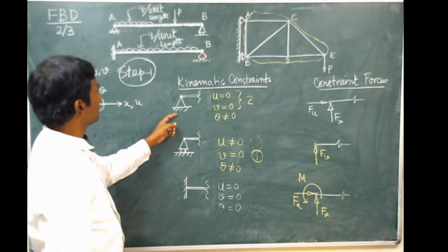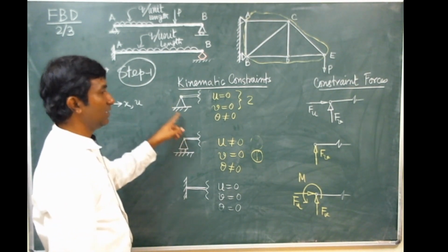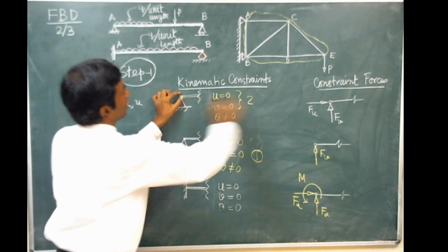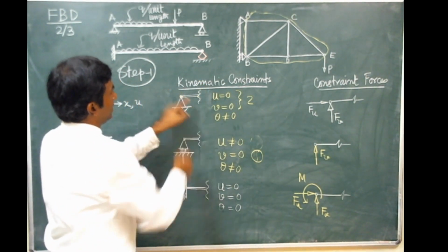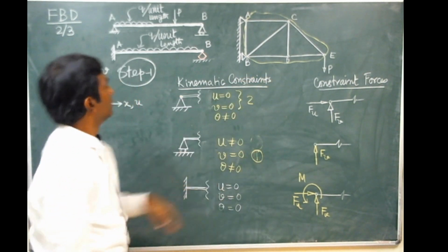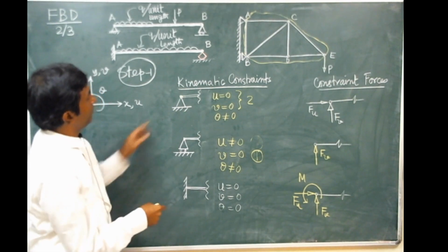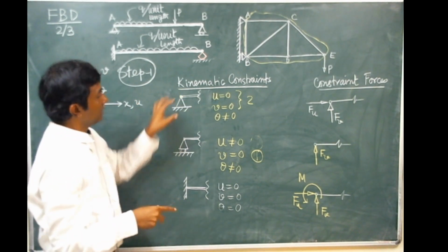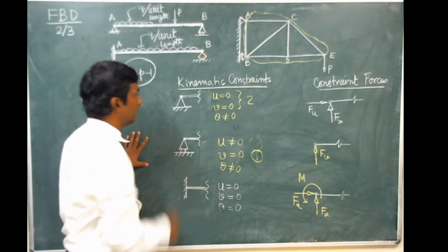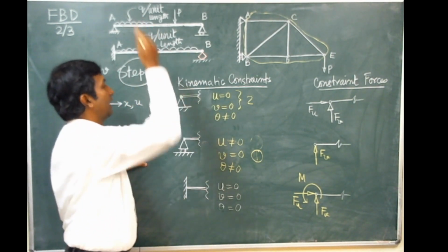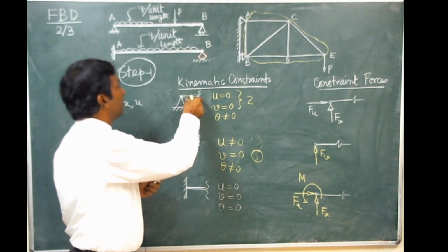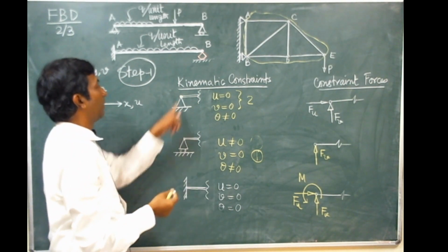You consider this case where this joint is a hinge joint. This is a member, an extended member, so we have not extended it. This is a formal representation, that means that this part is extended. So we see the meaning of that representation. This kind of representation means displacement is not allowed in the x direction, displacement is not allowed along the y direction, but this member is free to rotate about the z axis, about this point.